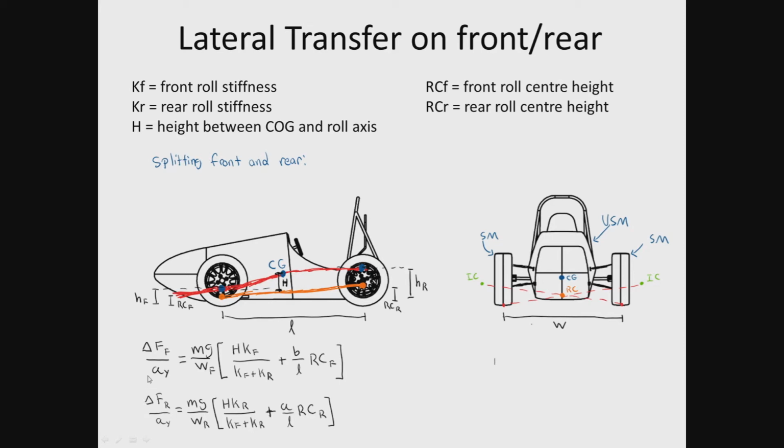You can't just assume that the entire weight transfer will be split evenly between the front and the rear and use that in your lateral force calculations. You'll end up with inconsistencies and you'll most likely not be using the full potential of your tires. Rather, you want to consider these systems independently.